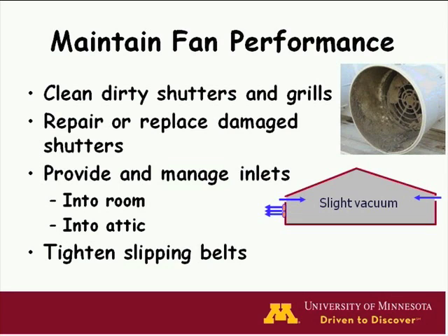You need to manage the inlets, and remember, if you have a system where you are using ceiling inlets and you're bringing the air through the attic, you need to have enough room to bring air into the attic space and bring that out. And again, many fans have belts, and if you have belts, they need to be tightened to maintain their performance.